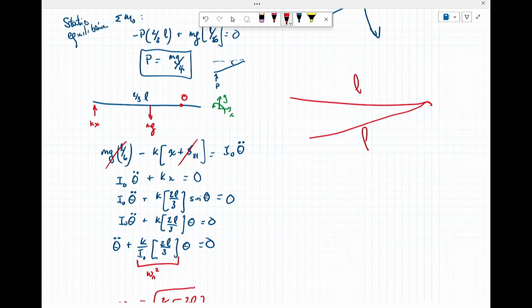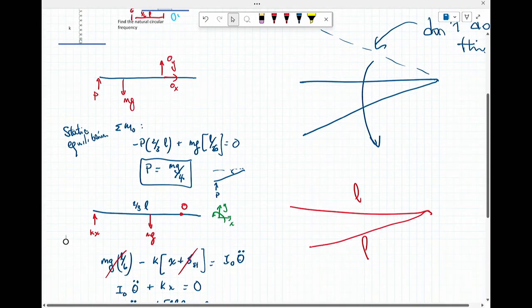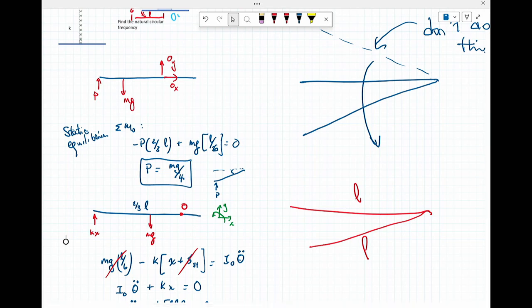Sorry, I just meant when we have MO at the top of the screen right there. This is negative P2 over 3L. Wouldn't we have to use sine or cos for that? Because in the case that it's resting down, it's not perpendicular to the body. Okay, and so that's, again, it goes back to this point that we are cheating. Oh, okay, so the rod is like this, we let it go down, but we pretend this and this are actually the same.